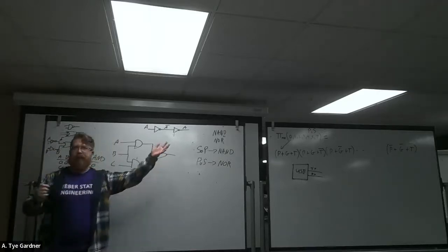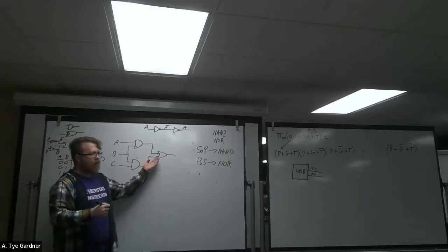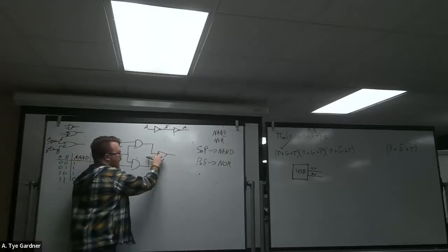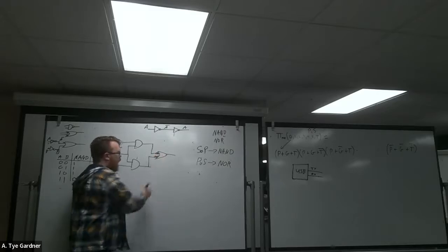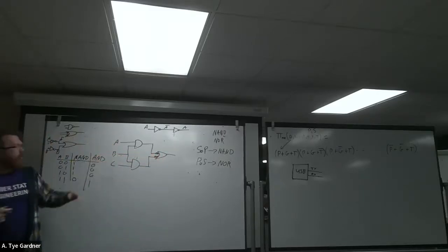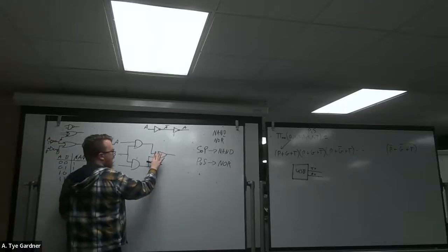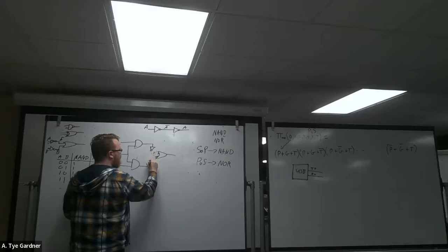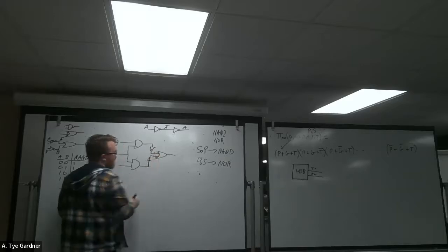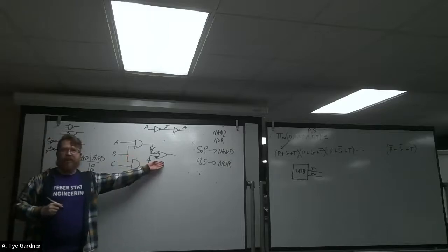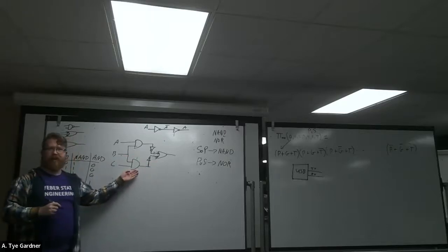Well, this is a NAND gate. I'm done. Well, not quite, right? Because I've now changed the expression. But if I put another bubble right there, double bubble, nothing's changed, right? Well, if I take these and pull them off, then it looks like so, and we're almost there because this is now strictly a NAND gate, and now I have to do something with this, right?